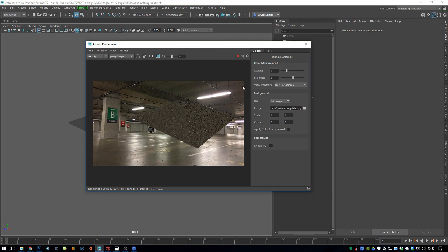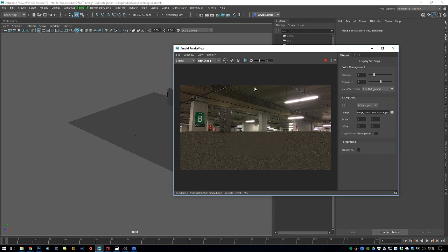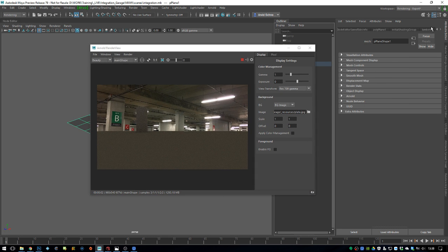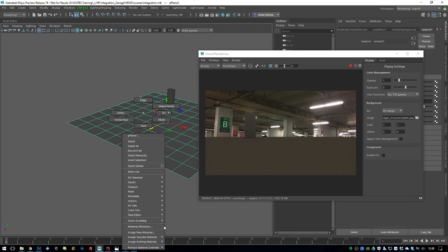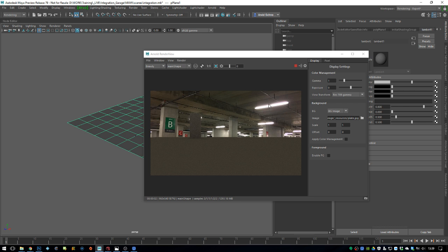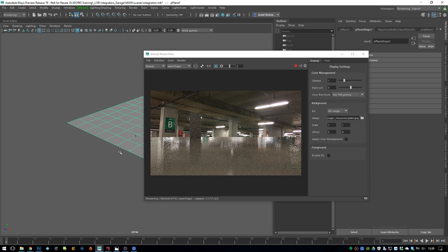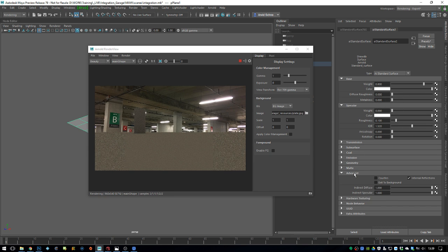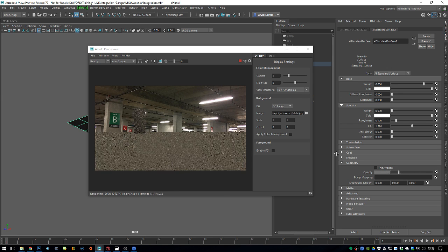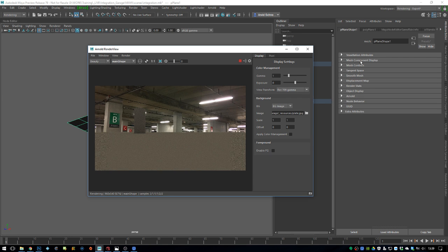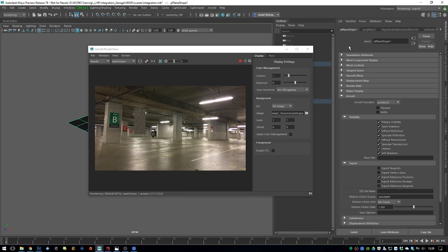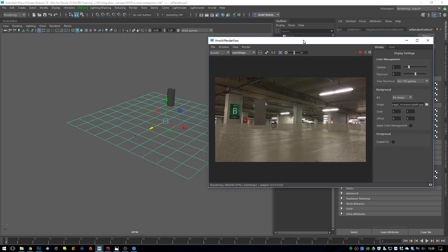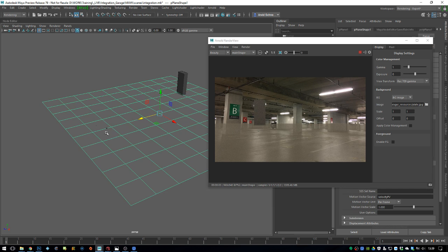So starting the render, looking through the main shape, and now we need to make it kind of see-through so we can align it with the camera. To do that, we need to change the transparency, or first assign a new shader. Standard shader. Did it assign? Yeah, now it did. And let's just do no specs, and we want to decrease the opacity. And for this to work, you need to change the shape node to be non-opaque. There we go. Back to the shader, bring in that again. And now you can see the lineup. And obviously it's not very good so far.